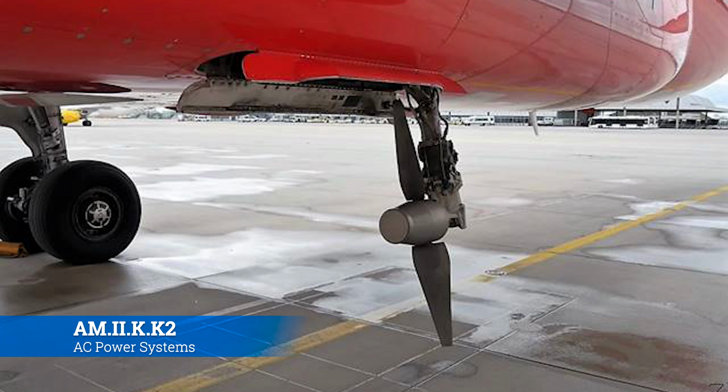In most cases, the transport category aircraft also have at least one or more AC backup power sources, such as an AC inverter or a small AC alternator driven by a ram air turbine, or the RAT, that you see pictured here on your screen. Now, during an emergency, this will deploy and it'll start to spin because it's basically a little wind turbine, and that produces AC power that will drive some of your key systems to maintain life, maintain flight.